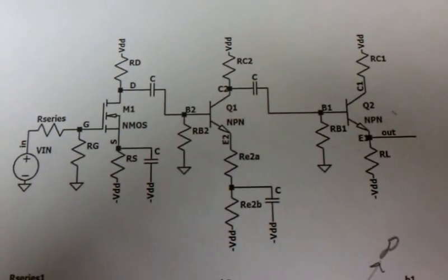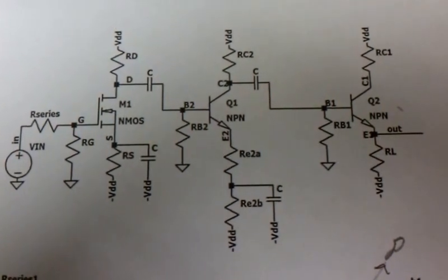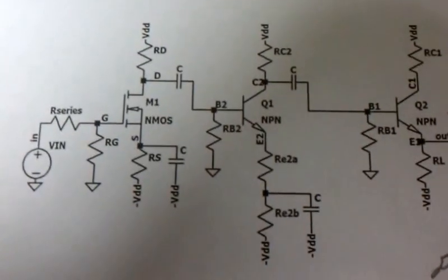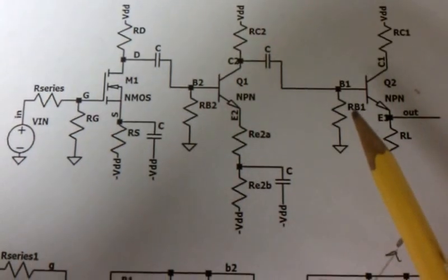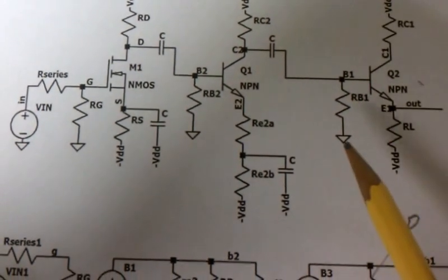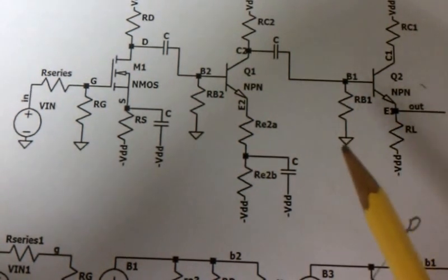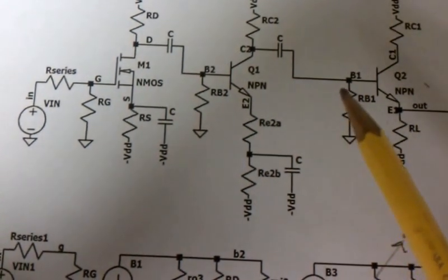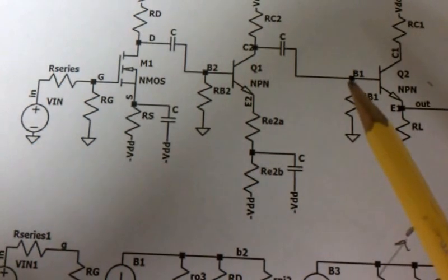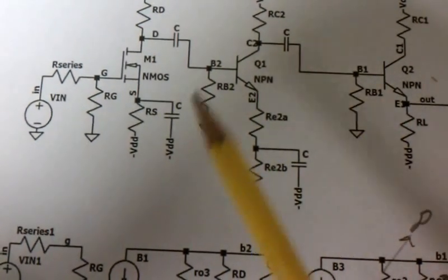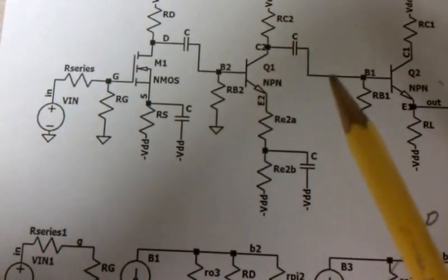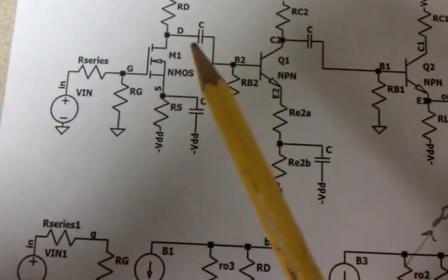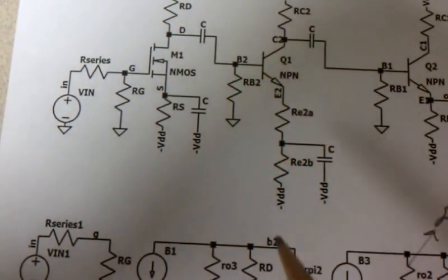Let's solve for the voltage gain of this multi-stage amplifier. Before we begin, we should check to make sure that there's not any problems. For instance, what if this resistance was 1 or it was shorted? The gain would be 0 because the input resistance on that stage would be 0, and it wouldn't matter what was going on in the rest of the circuit. Right? We can see that there's 3 stages separated by these coupling capacitors that couple the AC.